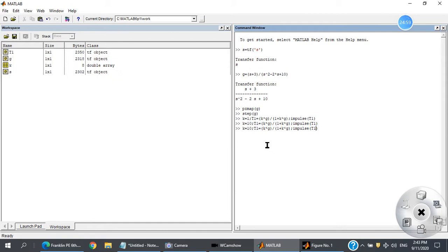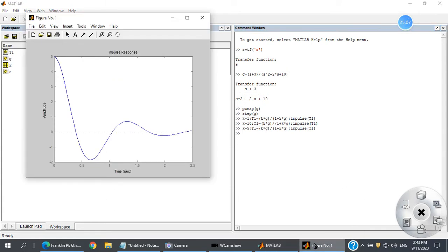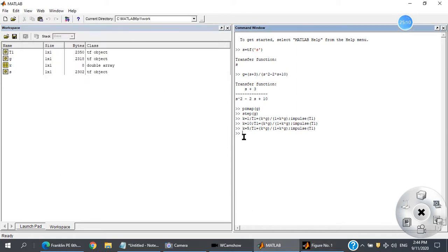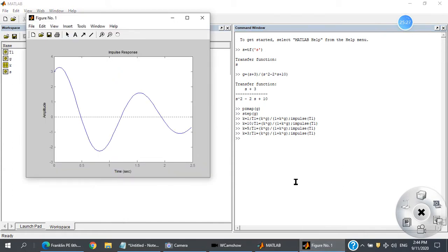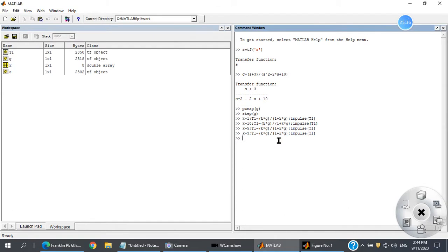So that will be a value between 1 and 10. I choose 5. We can try one by one. Okay, this is still stable, so I need a value smaller than this k. I choose the middle, 3. 1 plus 5 is 6, the average is 3. Yeah, this is close to the marginal case. The amplitude is decreasing, but not so fast. It's almost close. I think 2 might work. K is 2.